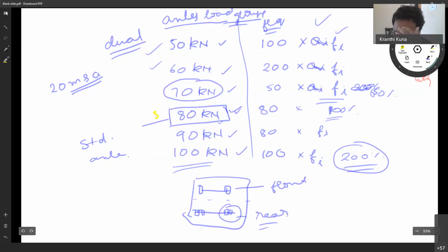So for this vehicle, you usually carry out an axle load survey and get the load group in which it goes. Obviously you will have a separate load group for the single wheel and a separate load group for the dual wheel. Say another vehicle has come which has another dual wheel axle, tandem axles. So you input this into a different group.